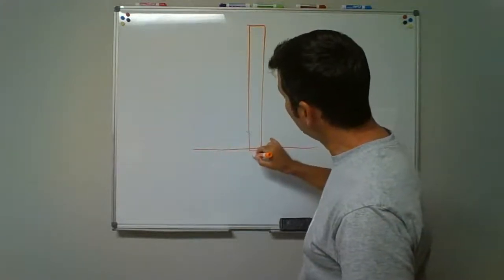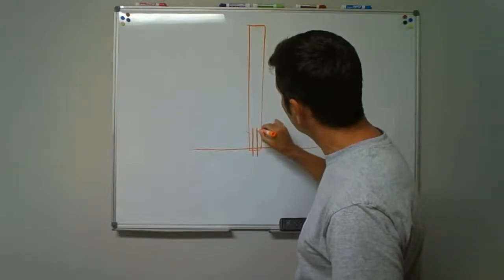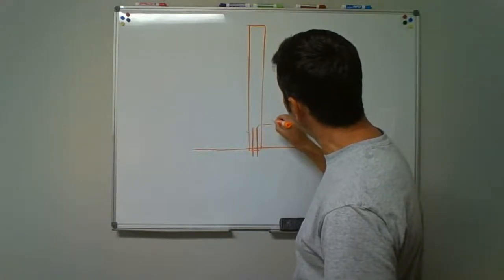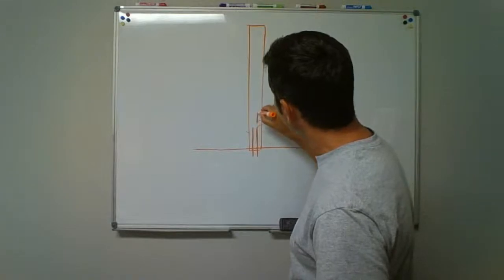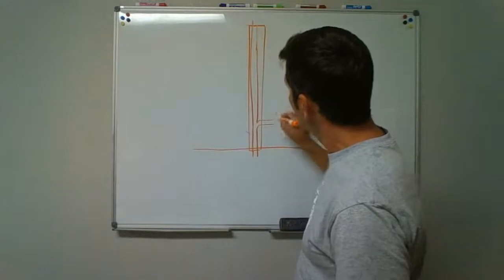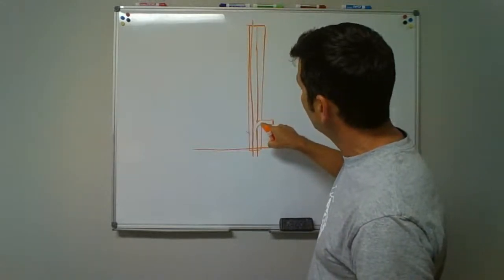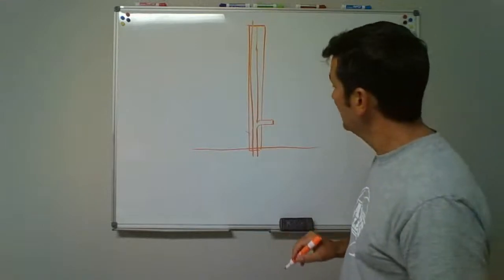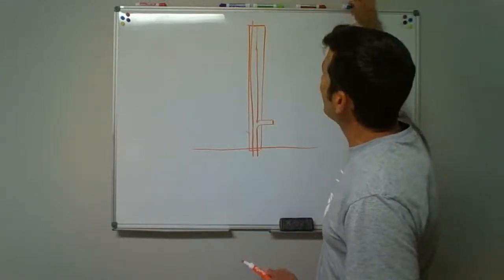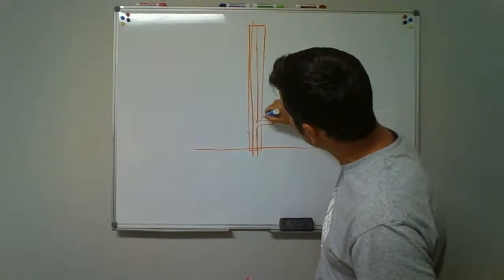We drilled a hole up through, we're sending the pipe up, and then we're going to turn out of the wall with a pipe. The vent pipe goes on up. So we're left with a pipe hanging out of the wall. When the drywallers come in and hang their drywall, they're going to cut or knock a hole around this.